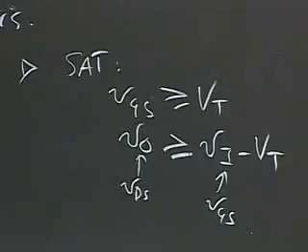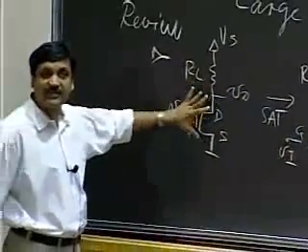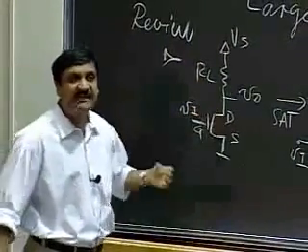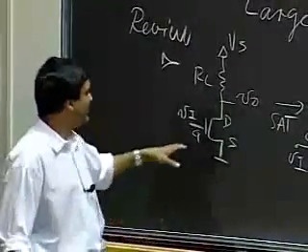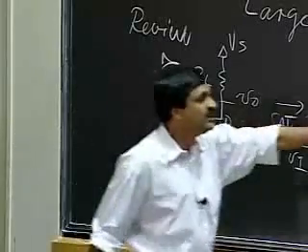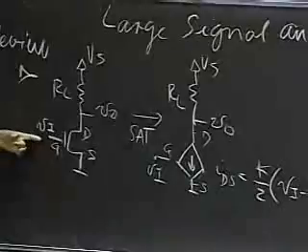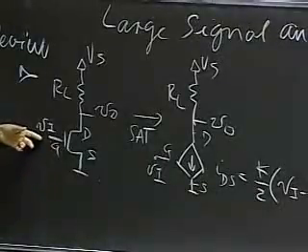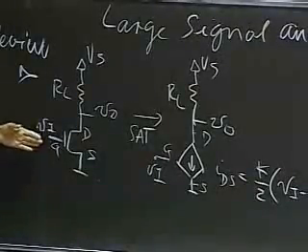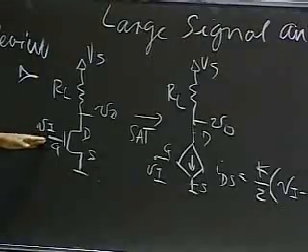So what are we really saying here? What we're saying is that we built the circuit using a MOSFET, and it's up to us as engineers to choose its operating points in a way that these two properties hold. So for example, to make the first condition true, I can discipline myself to operate such that Vi is always greater than Vt.